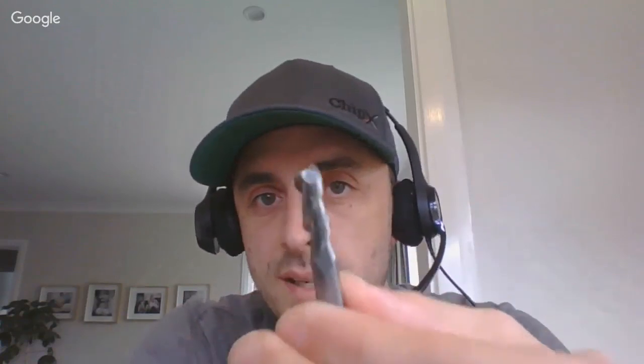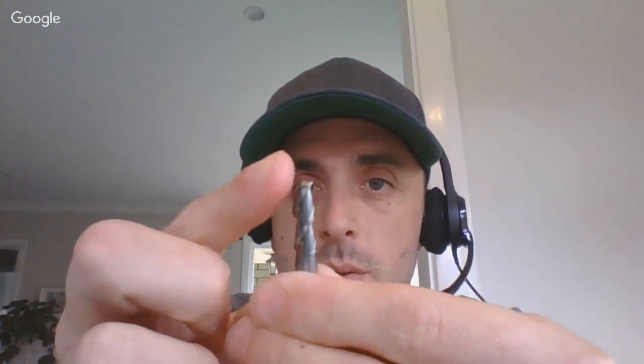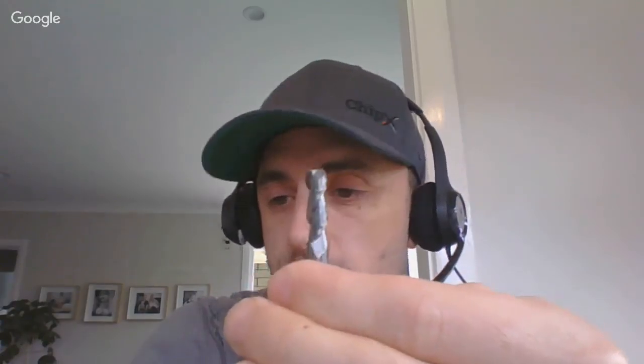So if you can find a surface foot per minute, or SFM, that's the common one that a lot of tooling websites talk about. That's what the Americans use. Otherwise, you might have millimeters per minute or meters per minute, because it's typically quite a high number. So you imagine that tool spinning at 20,000 RPM, the little cutting edge is traveling through the wood or plastic or metal or whatever it might be at a pretty good rate of knots.